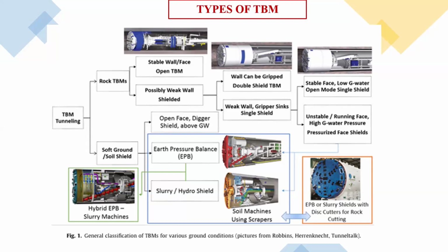It is like the movement of a grasshopper, which pushes itself with all its legs. In the same way the TBM pushes by giving thrust to the segments and then goes ahead. If it is a single shield TBM, the problem is that it cannot take the thrust from the rock, because it is such competent ground.